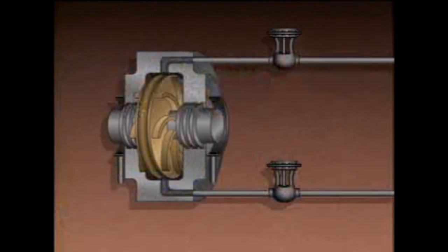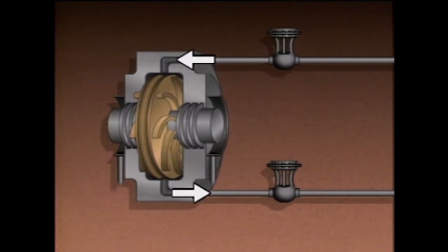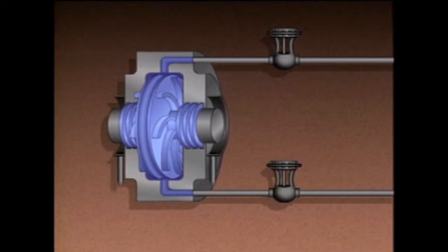A second alternative to steam seals is water seals. When water seals are used, water is pumped through a special gland to minimize leakage. A gland is a device used to create a seal. The advantage of water seals over carbon seals is that their parts tend to last longer. A typical water seal uses an impeller that's mounted on the shaft to circulate water through the gland. The circulating water fills the opening between the shaft and the casing, preventing leakage.